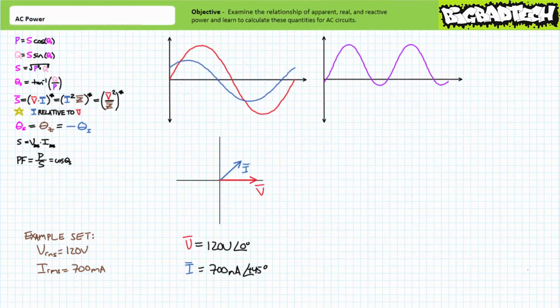Power analysis needn't be limited to scenarios with lagging current, but can also be calculated for occasions in which current leads voltage. Note, because of predefined sign conventions, capacitive scenarios in which current leads voltage, reactive power is assumed to be negative. Here's a plot of voltage and current where current leads voltage by, let's say, 45 degrees.